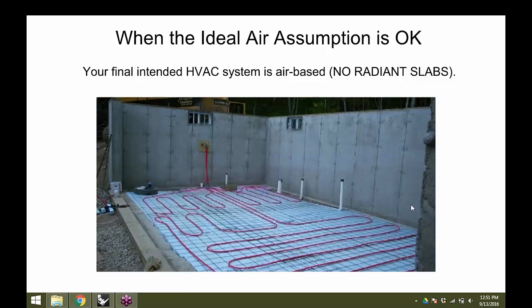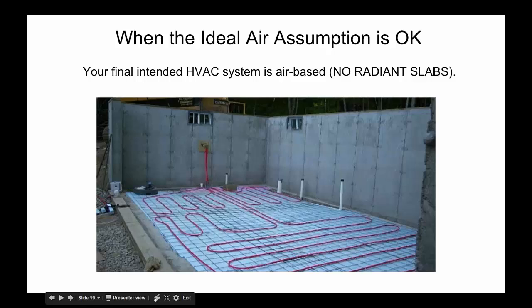Luckily, I caught it in time for a project where I was using an ideal air system to start off with, and we were ultimately going to use a radiant slab system, and the effects of different strategies were just much different for a slab system than for an air-based system, which is really what an ideal air system is. It is air-based. It's delivering hot or cold air to the zone.